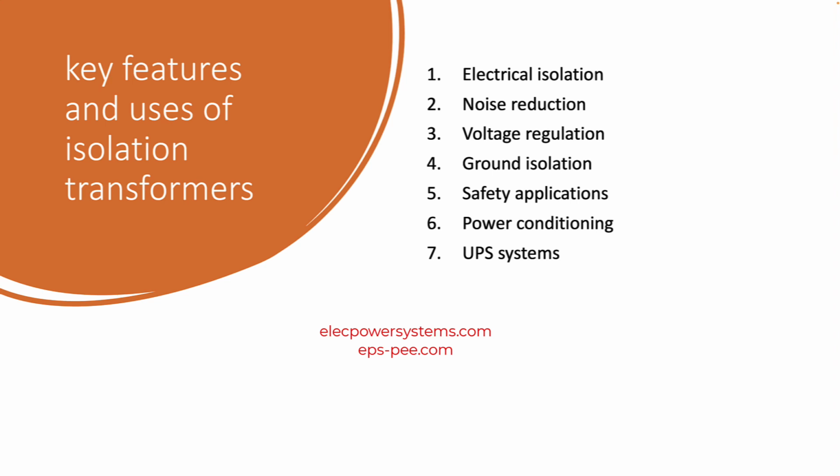Safety applications. Isolation transformers are commonly used in medical facilities and laboratories where electrical equipment needs to be isolated from the main power supply. They provide an additional layer of safety by protecting patients, operators, and sensitive equipment from electrical faults and surges.